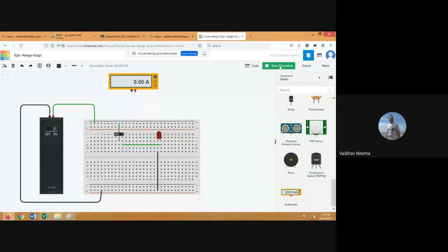Now we do this simulation, and if I close this switch, it means the 1.5 volts, these two terminals get short circuited. It applies the 1.5 volts to the positive terminal of the LED, and the negative terminal is connected with the ground. It means you apply the high voltage. You put this LED into the forward bias condition, so it will show you the color. It turns on when your switch is closed, turn off, turn on, turn off, turn on, turn off.